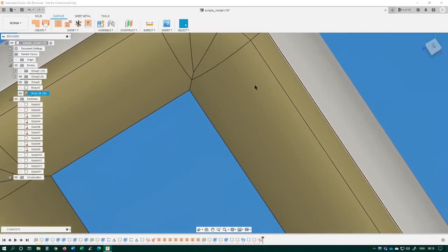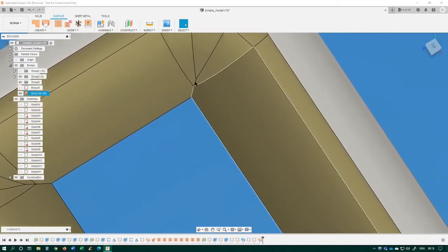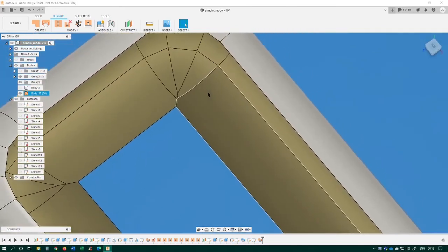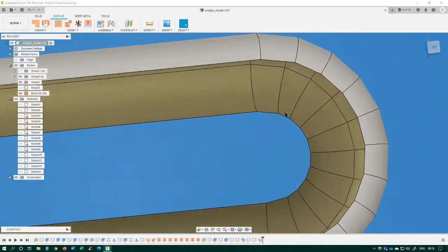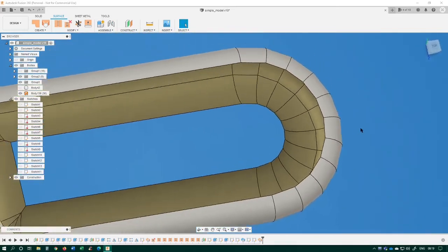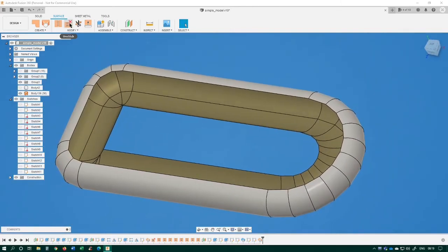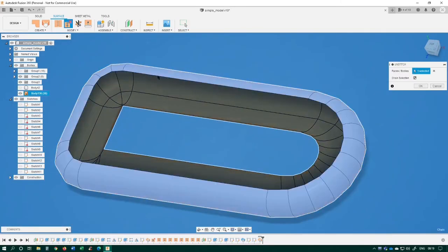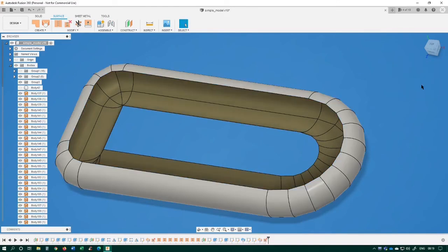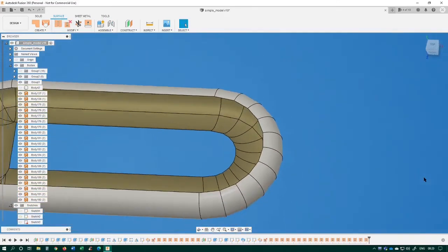Be aware that with very tight curves, as in curved corners, if you put too many short sections in, you will find the skirt doesn't join to the hull. In this example, I've done this, and you can see the resultant skirt makes an awkward join. In practice, I would probably just do 2 sections across the corner at most.